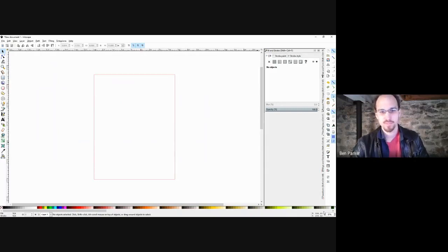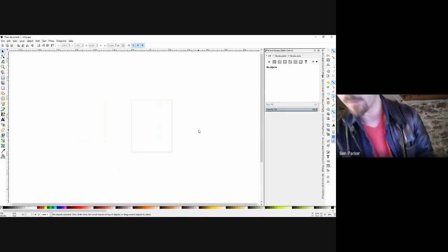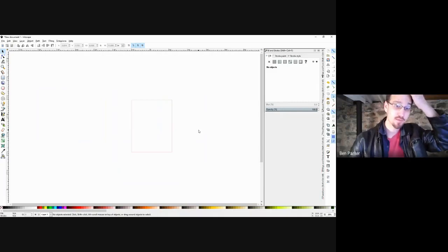You can also use this little thing off to the right side to set the zoom to a very specific number. But usually you're going to use either the plus or the minus sign or Control and the wheel for a nice smooth zoom in and out. Okay. So Inkscape usually has, for any function, a lot of different possibilities, and you'll get the hang of which ones you like the best, and sometimes different situations call for a different function or a different version of it.